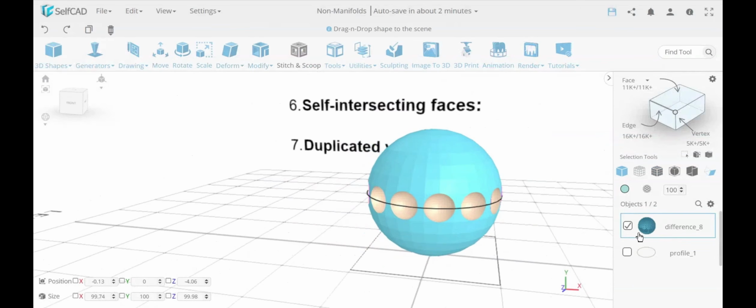The reason this is helpful is because union or any of these other intersection tools will work on each object individually. So if you think about 12 copies, 12 objects plus the sphere as the 13th, you need to check each object against each object. This multiplies and becomes quite extensive. If you have a more complex object, this may be too much and you may have to do a few at a time. By grouping them together, either merging or grouping, I tell the tool this is one object, and then it only has to intersect one object with the other.